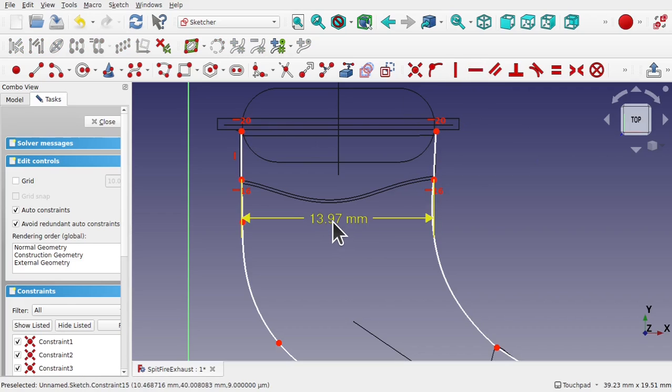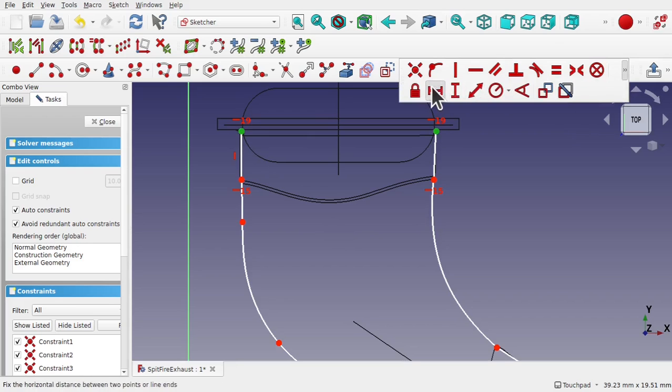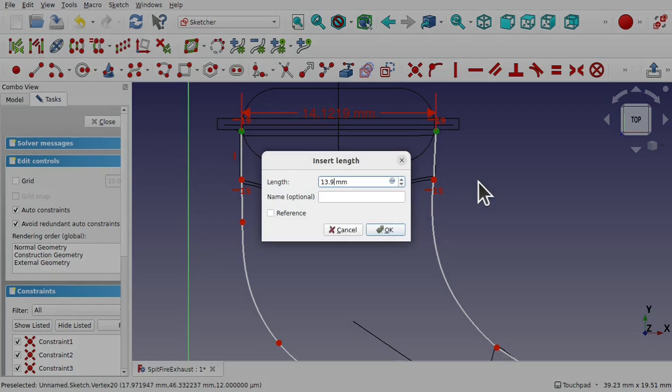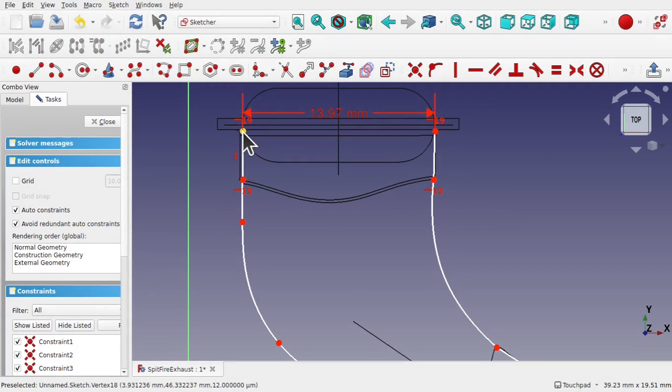And 13.97, let's delete that and set the length here. Use a length 13.97. Let's pull those in, but we just want to be careful of how this curves up and how our transition is between those. So I'm just looking and thinking something like that. This affects our surface, so if we have tangency across here, we get a better surface. So I'm thinking something like this.